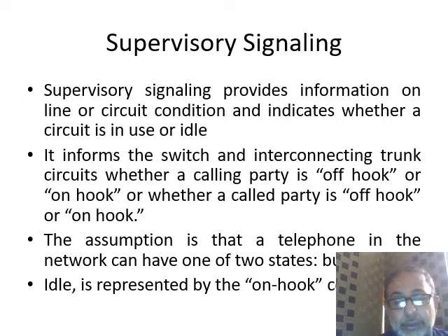So this is one of the important functions of the supervisory signaling, because the telephone exchange needs to know that either you have your telephone set on hook or off hook. If it is on hook, it means that it is idle. Otherwise, it means that it is busy.